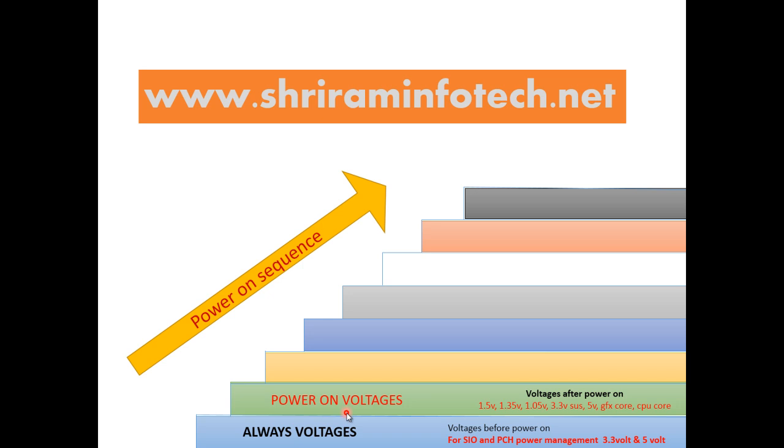Once the motherboard gets the power, the next signal is generated, that is power good. The power good signal is the confirmation signal that all power planes are steady now and they are ready to work, and that signal is called power good. After that, the motherboard gets reset.